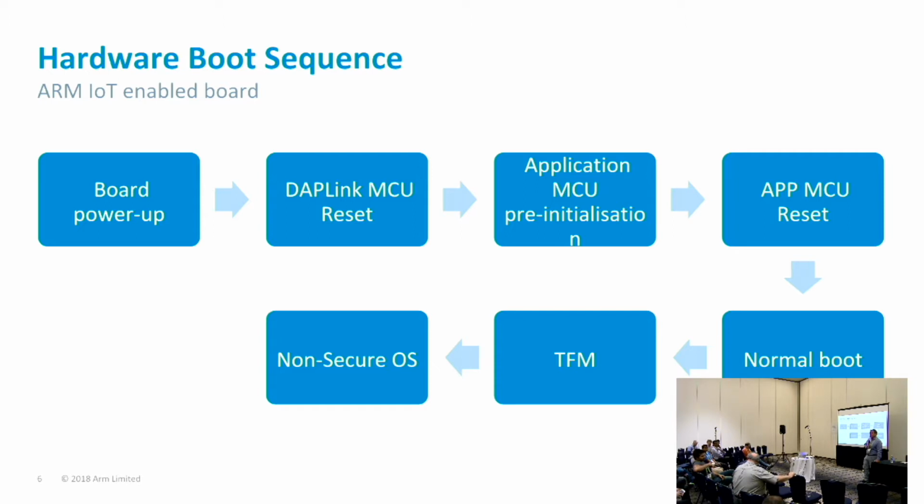You need a way of flashing the device, and if you have a production device which doesn't have a lot of housekeeping hardware, then you could use the firmware update process for that particular device, and burn or flash the new binary image. So all of this infrastructure is just for letting the new binary be put into the device. And if you have a device which doesn't have the extra peripheral, you could use the firmware update process to put in new firmware, do a reset, and then use the harness provided by the CI infrastructure to run the runtime tests.